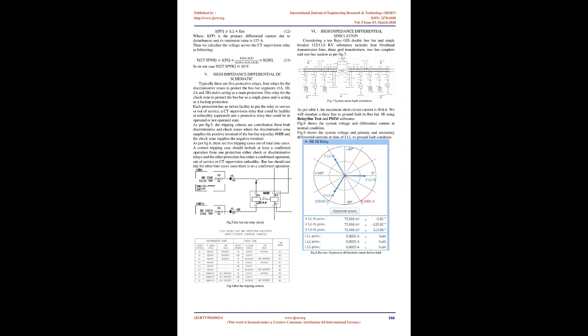The following practical equations are commonly used: equations 4 and 5, where I_mp is the minimum sensitivity primary current, and K_m is the CT ratio of the lowest load current bay.